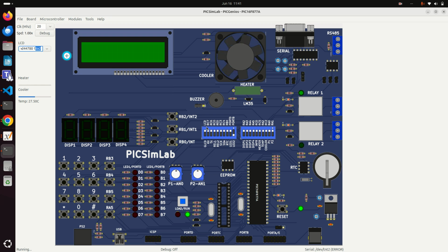What does it mean? It means you can show 2 lines; the LCD has 2 lines. Here you can see this is the first line and this is the second line. Boxes are there, right? In total we are able to print 16 characters in the first line. The 2 indicates you have a total of 2 lines, and 16 means each line can represent 16 characters, and the second line can do the same. That's why it is 16x2.